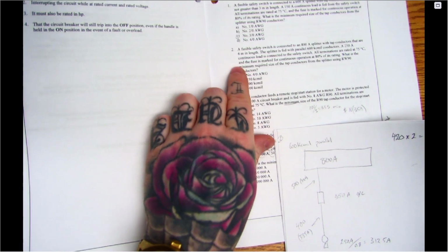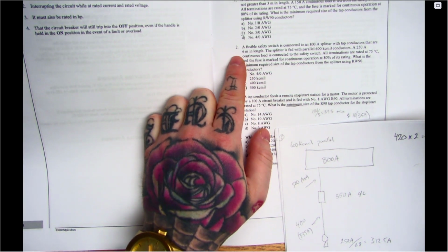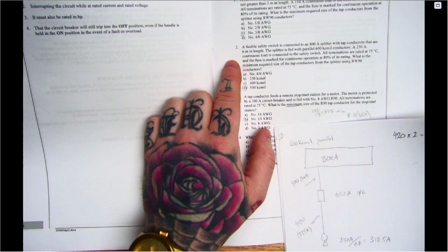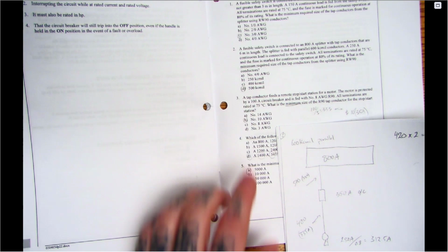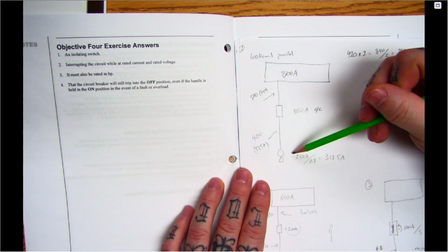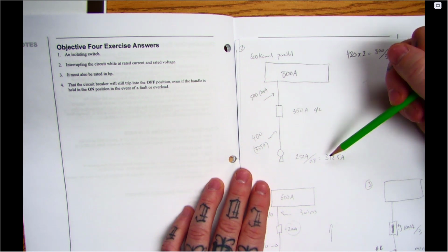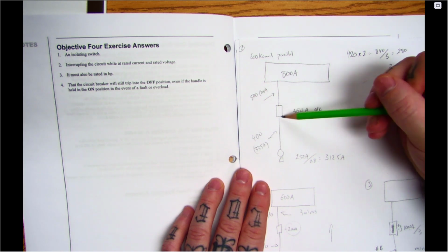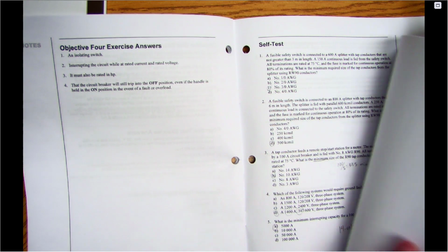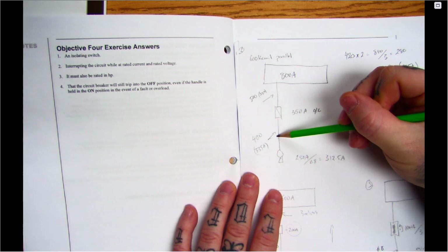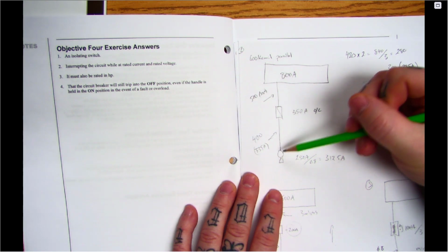Okay, fusible safety switch is connected, so there's number 2 here. An 800 amp splitter, it's fed with parallel 600 kcmils, 250 amp continuous load is connected to the safety switch, all terminations 75 degree and 80% operation. So again, I start at the bottom, I get my load, I increase it because it's continuous, so now I'm using the 312.5 amps to size the conductor from my fuse. We run 400 kcmils from the load, not necessarily a motor.